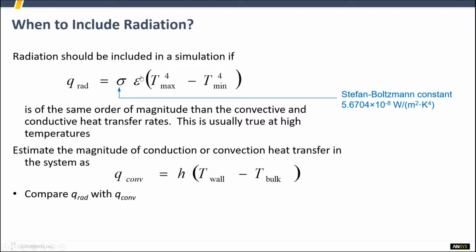The emissivity of the materials. So if black body is the most emissive, white body is the least emissive. And you can see here it's a function of the temperature difference to the fourth power. Okay, so really we only consider thermal radiation as a heat transfer mechanism when we've got really high temperatures, because generally it's actually quite an insignificant or negligible energy transfer phenomenon.